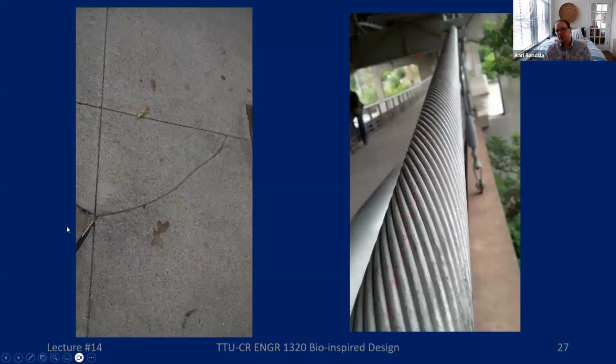And so we do very similar things, right? So if you think about this as a sidewalk, you can see there's a right angle here. That right angle formed a crack, but that crack didn't just keep on going. It went to this next little border within the cement, and then it ended there. That's why our cement pieces are always bordered off, right? If you think about a sidewalk, we could just have one long concrete thing, right? But no, we put these borders in so that if a crack forms, it will go to that border.